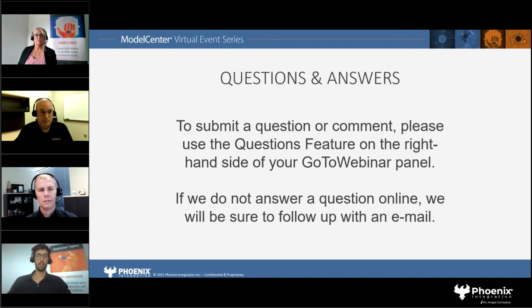Yes, it is. Here I was just showing the simple requirement verification process. You can come up with more complex scenarios. You can write your own script inside Model Center MBSE in which you can not just use comparisons, but more complex scenarios with if loops, depending on the values of certain parameters, for instance. And this is feasible inside Model Center MBSE. So yes, you can come up with your own more complex requirements analysis. That's possible.